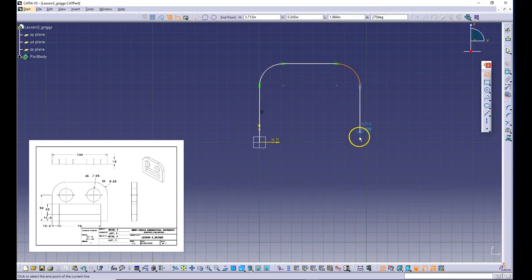And then drawing down to the baseline where I started. And you can see that that horizontal line turns blue to help guide you to that connection. It kind of helps you create symmetry whenever it's possible. Click that point, go back to the origin, and finally click that point there to end off my closed loop.